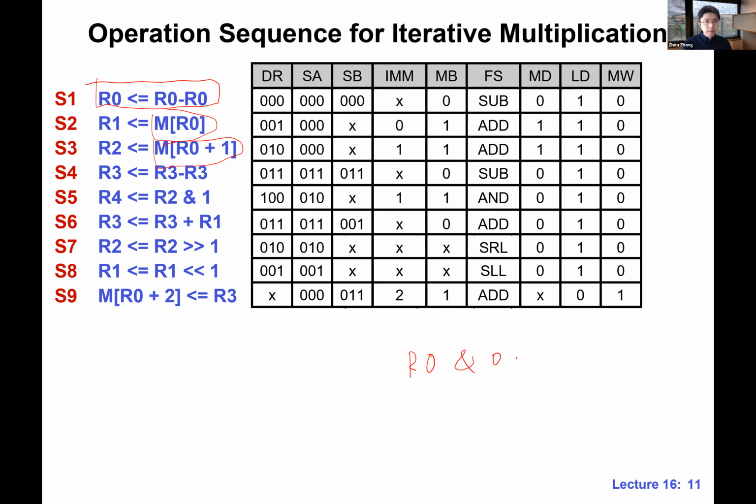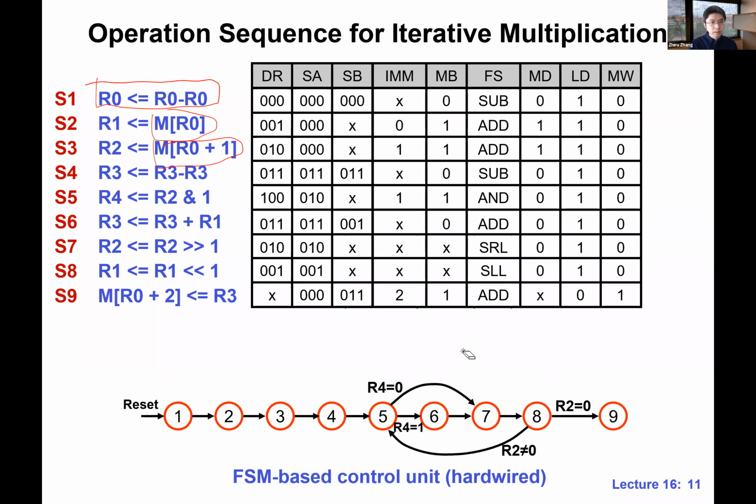And this is the complete control sequence, or control words. You just have to execute these instructions. Although we cannot just execute them one line at a time, because there are some loops. We need to jump back at a certain point. Also, we need to make branches. One way to really implement this control unit is to leverage something that we have already learned. We can just write out an FSM. So basically, that's why I have these state numbers.